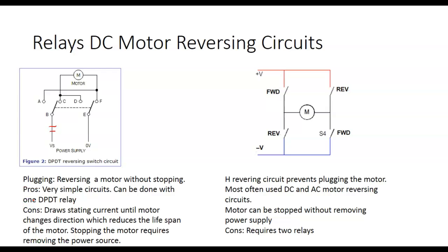So this is one big advantage fluid power motors have over electric motors. They don't have starting current. You can reverse those suckers in a heartbeat like that. Don't hurt them at all. I mean, you're just doing it with pressure. So that's one big advantage hydraulic or pneumatic motors have over these.